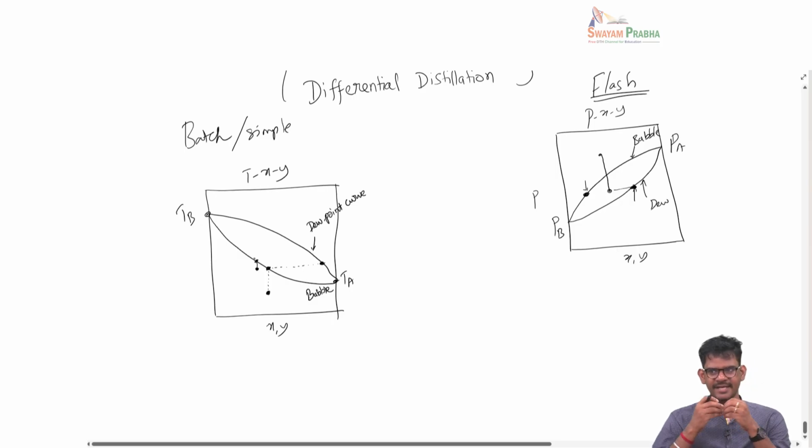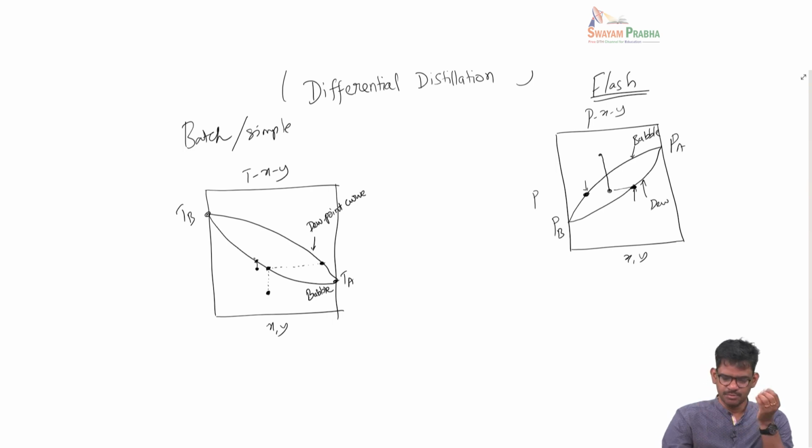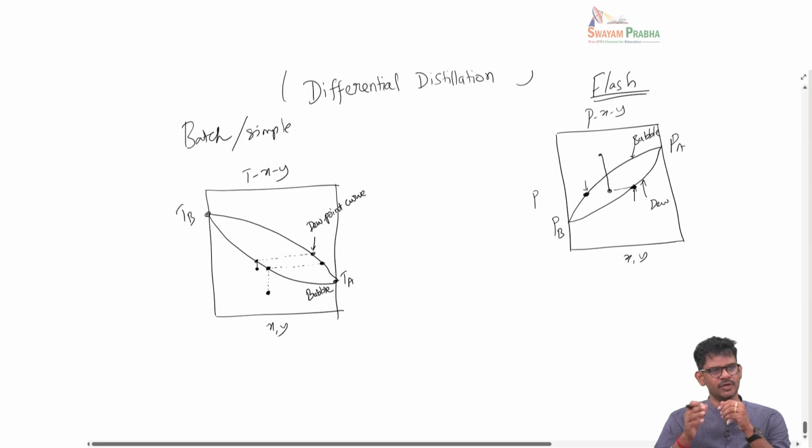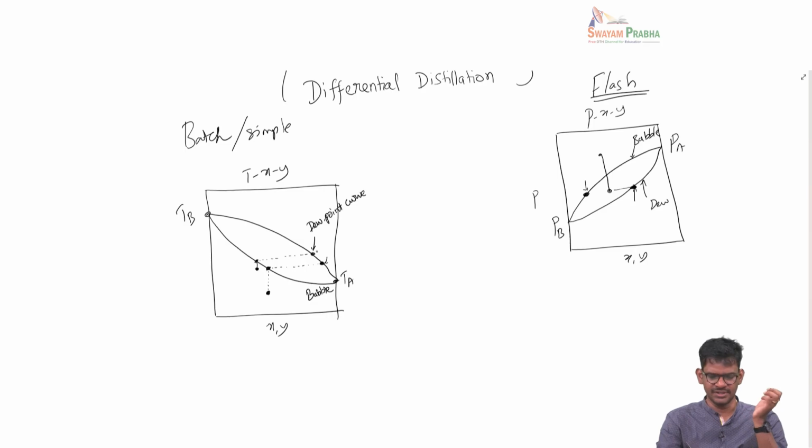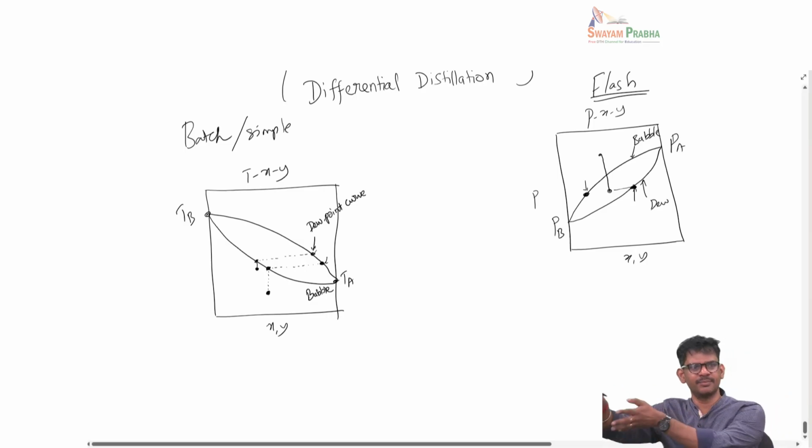Okay, so we are adding a little extra heat, and then what happens is we reach a new bubble point. At this point, we will establish another vapor formation because of flash. Let's say here also I am taking this vapor away and mixing it with the vapor that came before. So I am collecting it. I am taking this vapor and putting it in the container. The next fraction, when it comes here, I am collecting that vapor, condensing it and putting it back into the